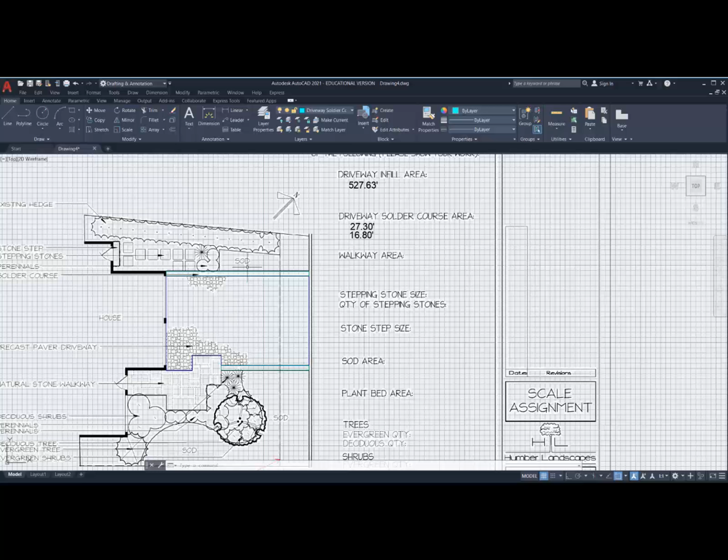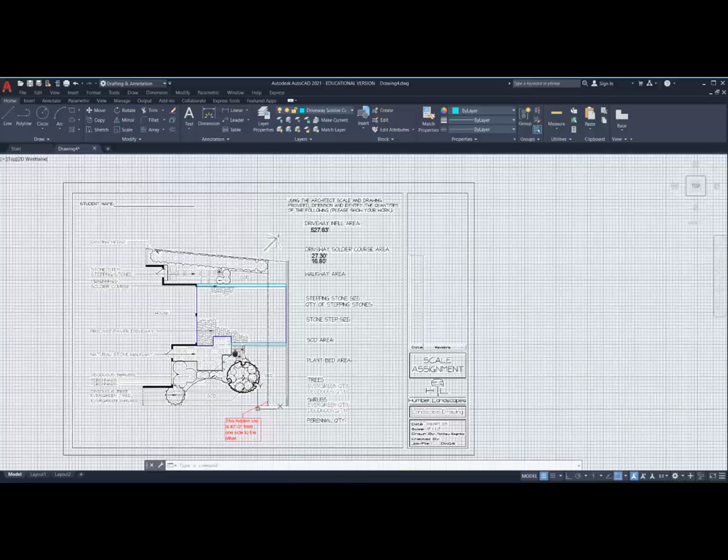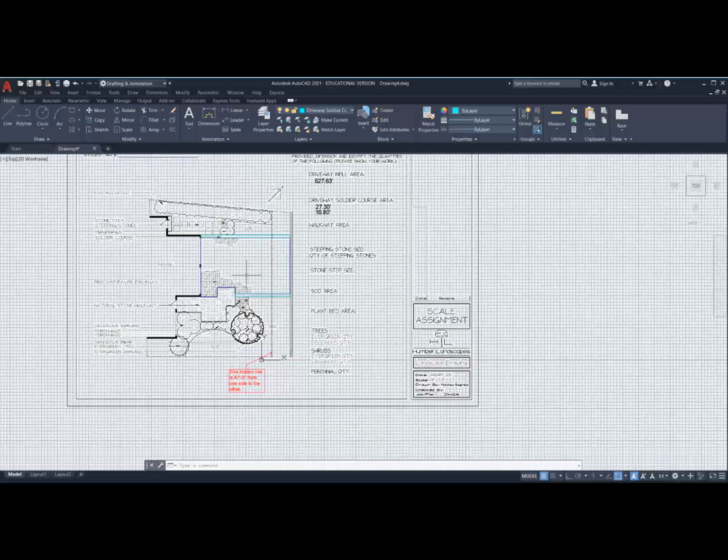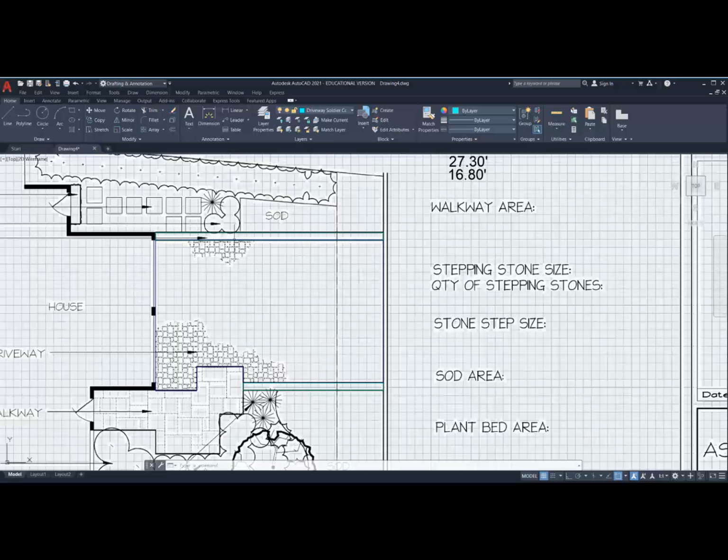And now by adding these two together, I can get the total soldier course area. And it's nice because I can always go back and remeasure in case I've got a number wrong or something seems wrong. And in that particular case, I can modify it and make sure that it is more accurate. If somebody wants to come along and increase the soldier course width and I want to maintain the outer edges, I can easily do it here using the scale command and scale the two objects together and allow me to recalculate the area of the infill quickly and accurately.